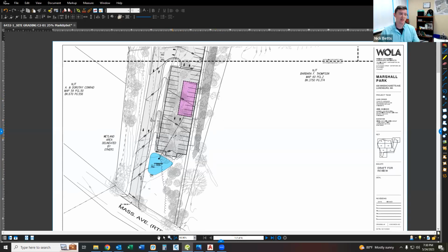The reason for the gravel parking lot was because gravel is considered less impervious than asphalt. So it gives you a lower volume of stormwater that would potentially be running off, which means that your systems to capture that stormwater can be smaller and smaller. There are other benefits, but again, I don't want to get too detailed.